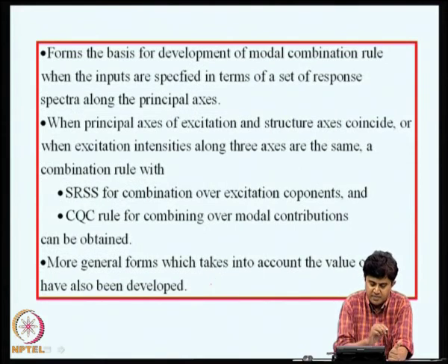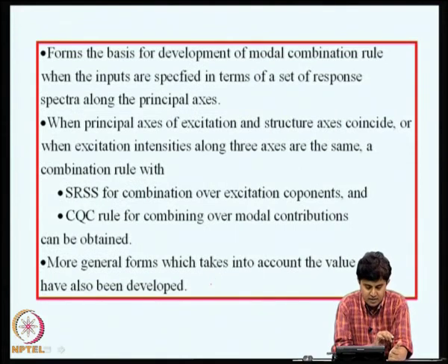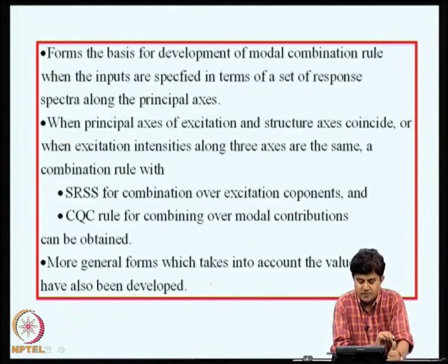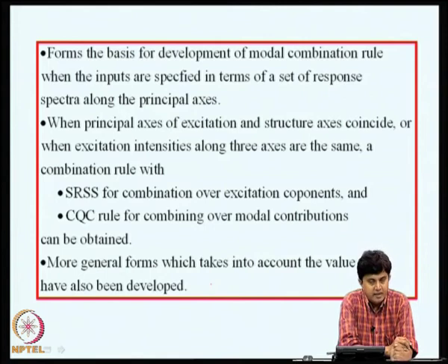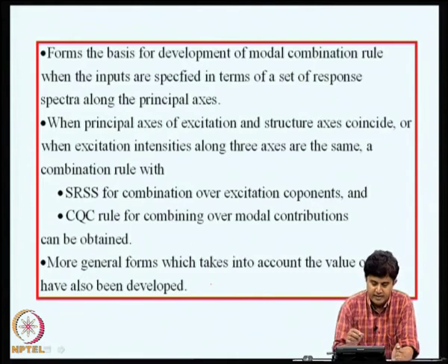Now, this will form the basis for development of modal combination rules when the inputs are specified in terms of a set of response spectra along the principal axis. The discussion so far has been under the assumption that we are specifying the ground motion in terms of power spectral density functions along the principal axis. But instead of power spectral density function, if response spectra are specified, then we need to evolve the modal combination rules, which now should take into account not only the combination over different modes, but also combination over different excitation components.